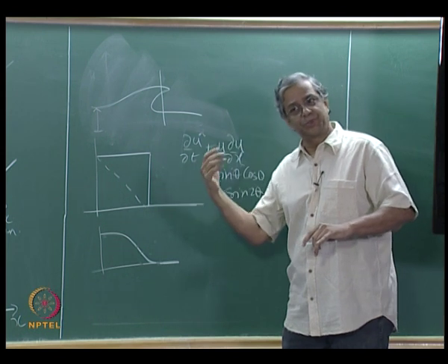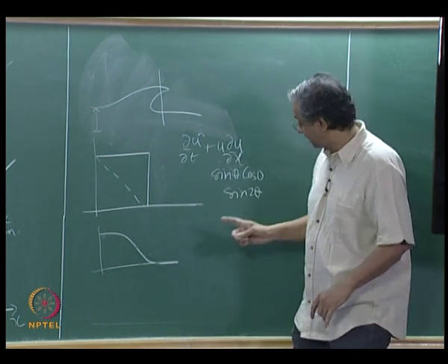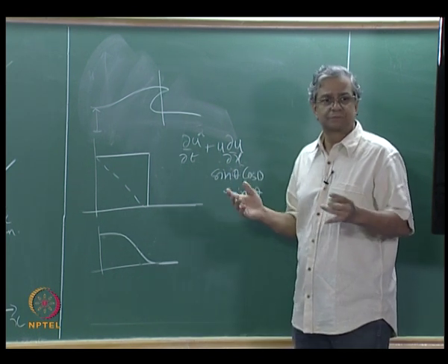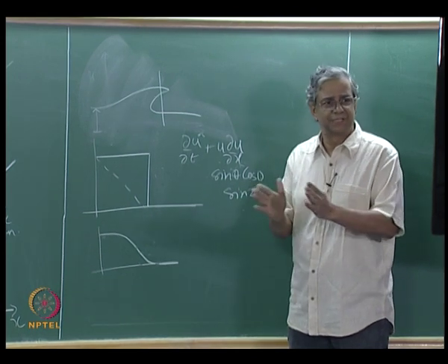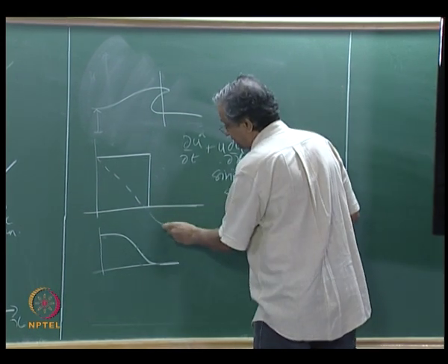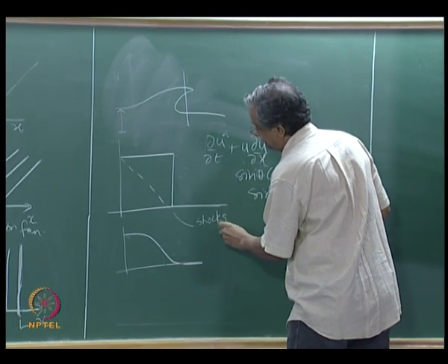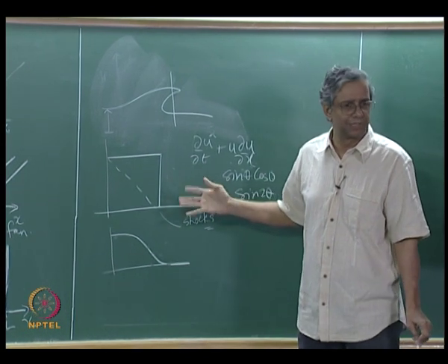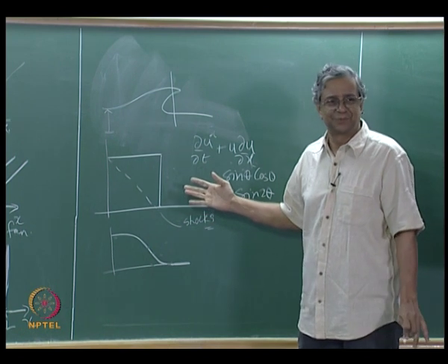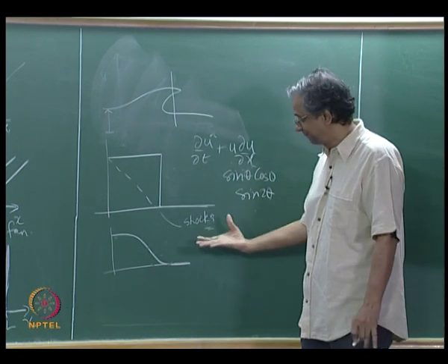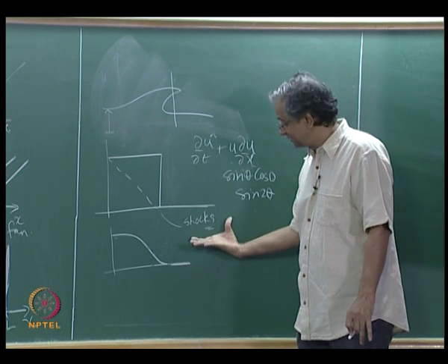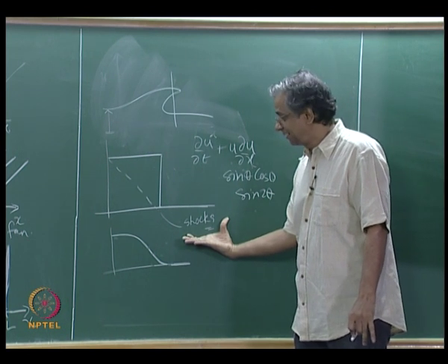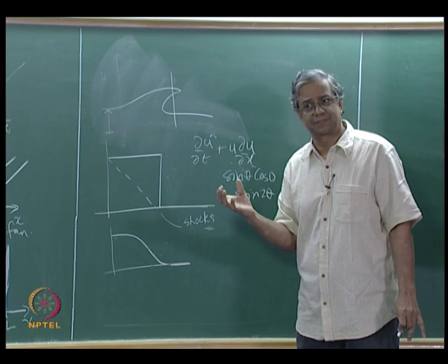So in the actual equations where you have both a viscous term and this quasi-linear term, both these effects are competing, and therefore what you have studied in gas dynamics is the thickness of any shock that forms. In gas dynamics these are called shocks. Occasionally in mathematical literature you may hear them referred to as an internal boundary layer, it is sort of an oxymoron, but if you know boundary layer theory you will know what they are talking about. So these are called shocks, and you know that the thickness of the shock depends on the viscosity.